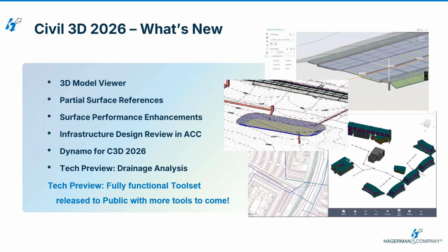For those that are using the Construction Cloud and Autodesk Docs with your projects, they have become infrastructure aware, meaning alignments. In my upper picture here, you can see I'm slicing a road. I can see what station I'm on. I can go to a station. I can measure station and offset, all those sorts of infrastructure-type things. Now that's a road example, but that could just as easily be a stream restoration, right? Same idea. It's an alignment.